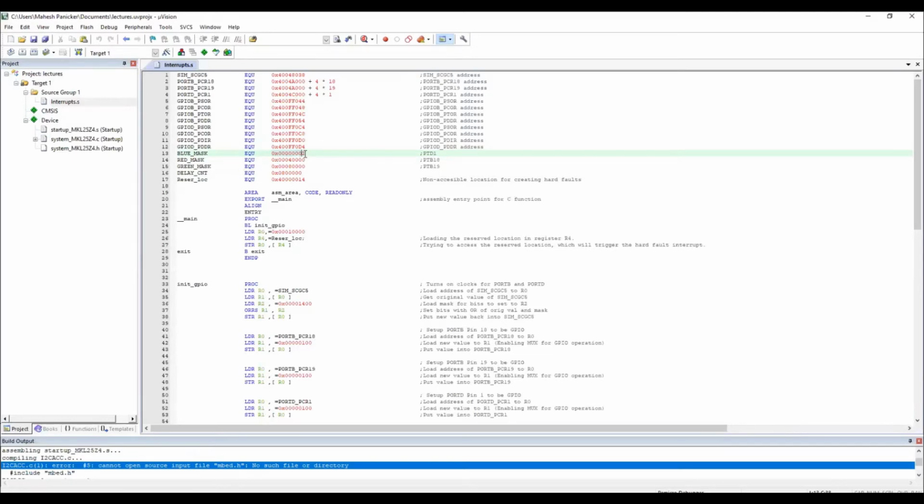Remember, this is hexadecimal, so 2 stands for 0, 0, 1, 0. Remember, it is port D's first pin. The 0th pin is 0. The first pin is what we are worried about, so you have to put that as 1. The other pins you don't have to worry about, all are 0. That is why it comes as 2 here, because 0, 0, 1, 0 maps to 2.